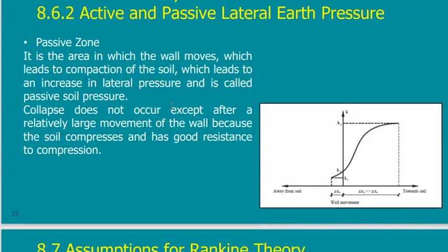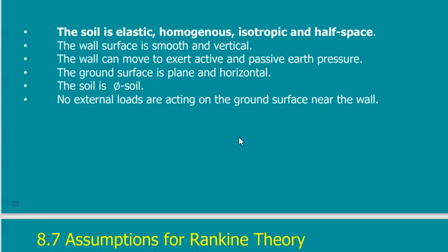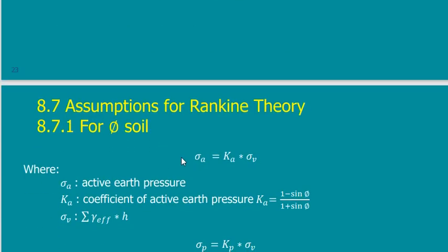So these are very, very important. If you don't know these, understand it, not memorize it, understand it. From this, what are the very important things? No external forces, phi soil, the soil is horizontal. This is, of course, it goes without saying. The wall is vertical and smooth. These are things that may change from equation to the other, so you have to know them by heart.